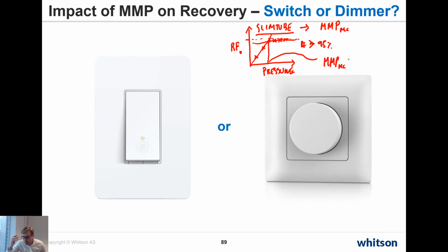So the definition is, okay, if we have a recovery of what's in the slim tube, which is just a porous media, higher than 95%, then we've reached the miscibility pressure. And then the question can be, why is it 95% and not 100? In theory, on paper it should be 100, but in reality, also with a slim tube in the lab, you can have physical dispersion and whatnot that leads it to be a little bit less than 100, but very, very high efficiencies.